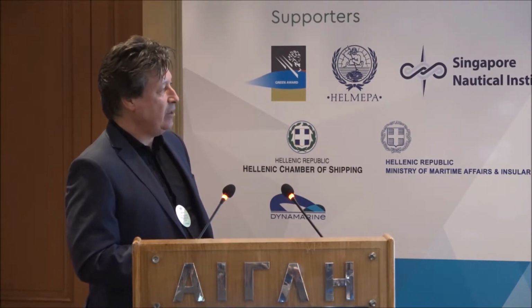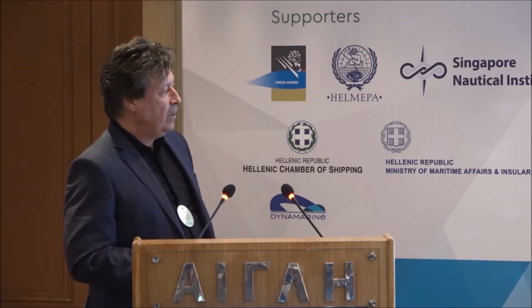Now, when you set limits, then any data that goes beyond a limit will show in red instead of a black font. Other data, such as all the hook and bollard and chain forces, are shown here, and the 6 degrees of freedom due to the waves are shown here. So normally they're not as important. The key things are the movement of the vessel, the percentage of line load, and the fender data.